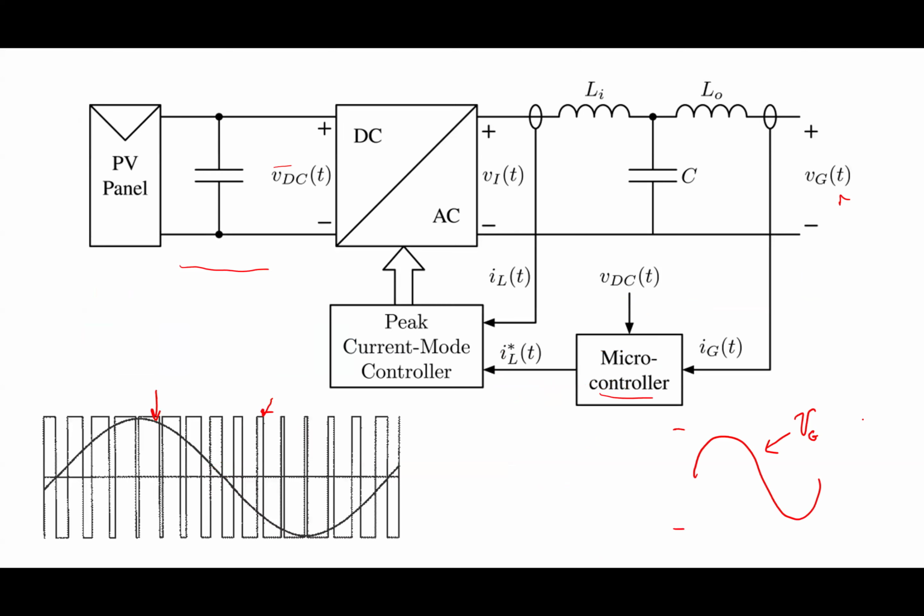Now here's a place where I often use that. Where would I apply any of this? This would be if I have a solar panel, a PV panel, a photovoltaic panel. This would be if I had a single panel. That's a DC output. If it's a single panel, this might be about 30 volts or thereabouts. And I might have, on the order of 10 amps flowing out of this in the middle of the afternoon. That's pretty typical for what I might see on a solar panel.